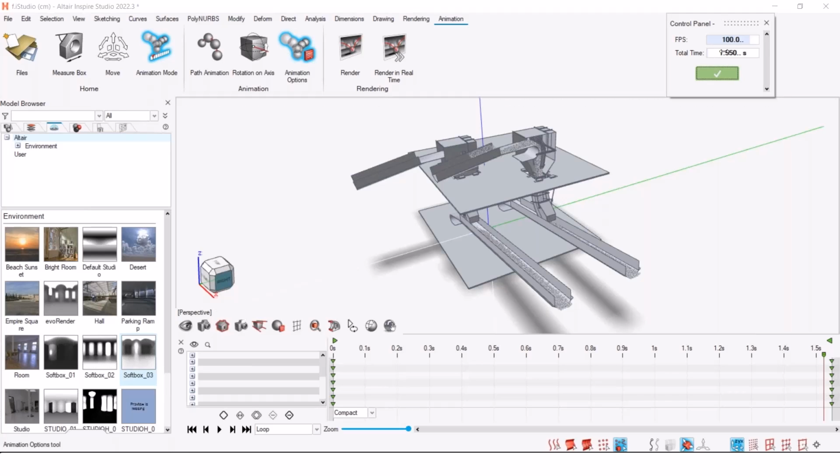So this is the animation that we have, and we can change a couple of things, mainly the amount of total time. We can reduce it if we want to not do the full thing. We can change the frames per second. This will be set by how many save intervals you actually have in your simulation. If you have a lot of save intervals, you can actually do a very, very high frame rate.